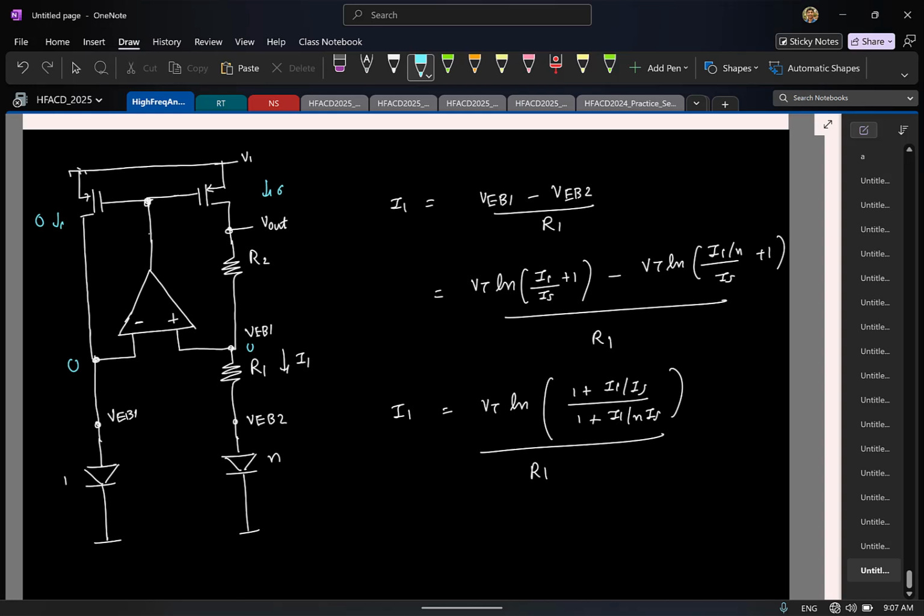But luckily it turns out this is not a really stable operating point, because let us say the circuit is dead, so this voltage is 0, for example. In practice there is going to be some kind of noise from all kinds of elements. So anytime a noise current is getting injected into this node, the voltage will try to increase, then the diode will start to draw current, and then the circuit kicks in and starts to work. So this is what we call a metastable operating point.